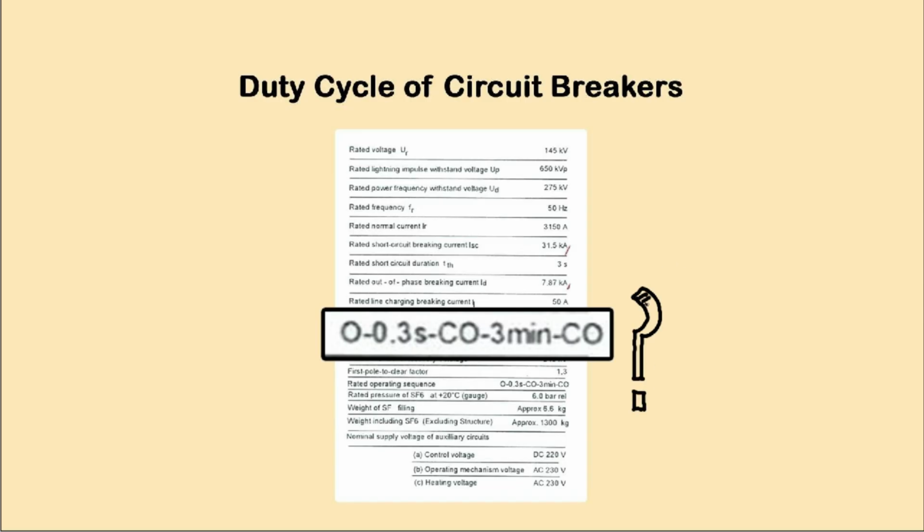When a fault occurs in the system and the breaker trips, it can reclose automatically to eliminate the unnecessary delay that occurs during manual operation. This is important because it has been observed that around 95% of faults in overhead networks are transient in nature, meaning they clear on their own shortly after occurring. During such transient faults, the circuit breaker trips. If we try to reclose the breaker manually, it takes time. To avoid unnecessary interruption duration, auto reclosing is used.